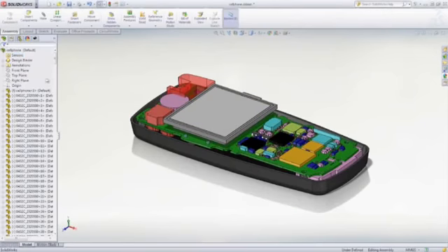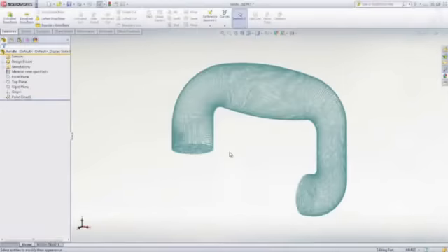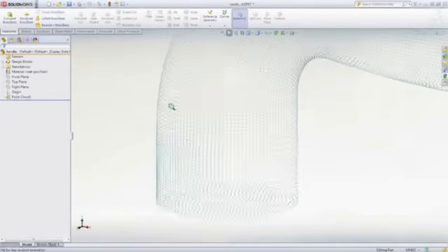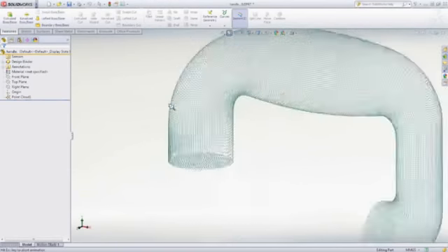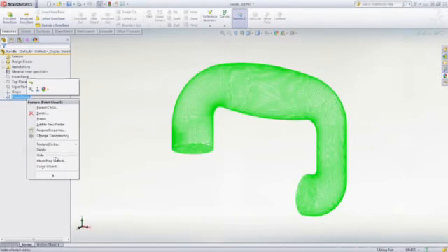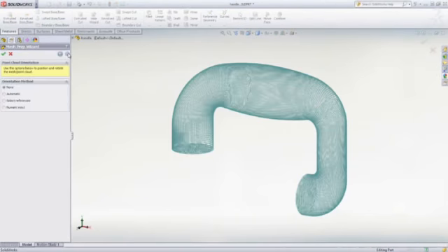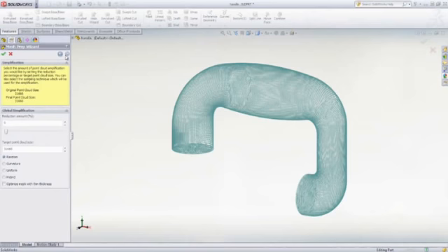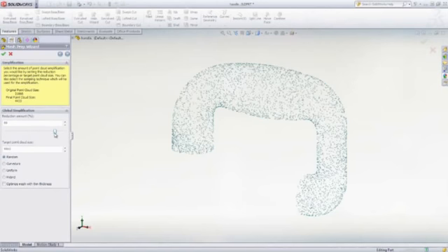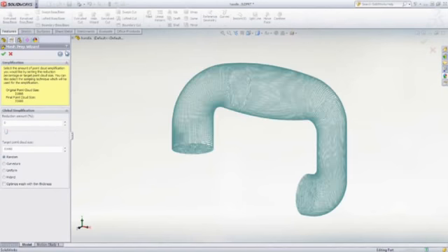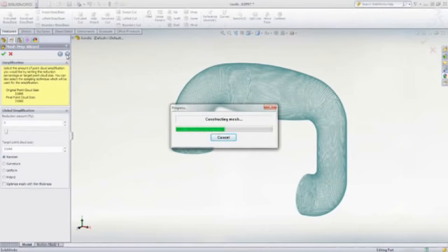When ready, the board can be built as a 3D assembly model from the customizable component library and readied for use in your designs. The Scan to 3D feature allows you to import scan data, mesh and point cloud files into SolidWorks and then convert it to a 3D surface or solid model. It uses a guided wizard to position the point cloud and remove noise or extraneous data such as fixtures that were used during the scan process. The simplification feature can be used to reduce the number of vertices to yield a more efficient mesh.